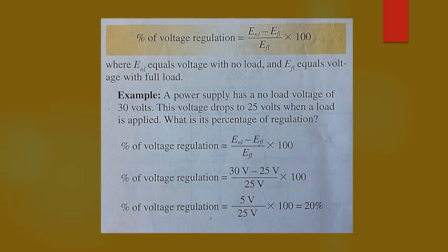voltage regulation? The output voltage of a power supply will usually decrease when the load is applied. This decrease is not good and needs to be minimized. The size of this decrease is measured in comparison to the no load voltage.